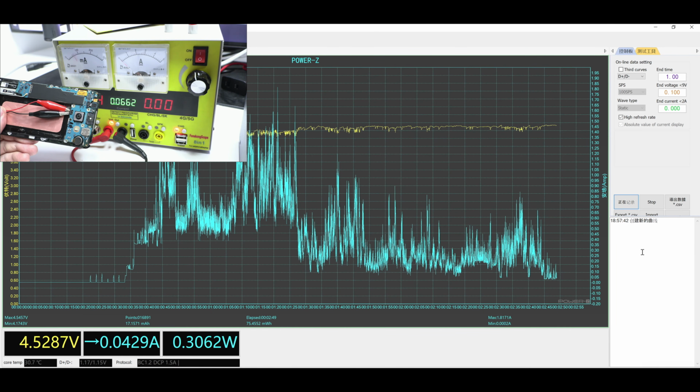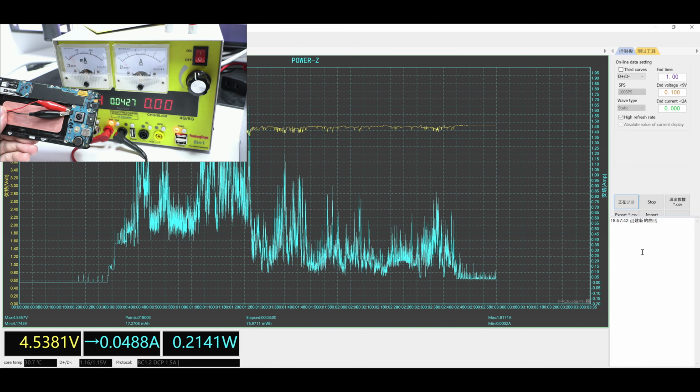This part is very important, and in this way you'll understand the power-up cycle of a mobile device. In less than 20 seconds you can already have a little idea of what failure the device has. In this graph, we can observe how the device enters energy-saving mode. We see a lower current each time and gradually it reaches 3, 4 or 5 milliamperes. This means that the motherboard has no consumption, which is very important to take into account.